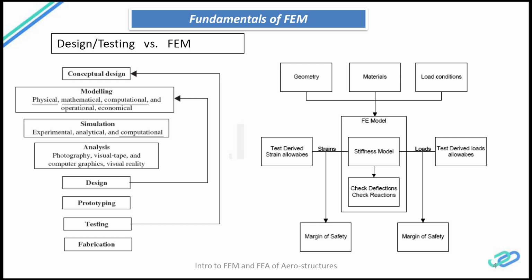And coming to materials, it's the material properties, your Young's modulus, Poisson's ratio, shear modulus, and various different things for various different materials. If it is isotropic, then you have a set of parameters, and if you are modeling a composite, which is typically orthotropic and anisotropic, you will have a lot more parameters, because the properties depend on the different directions.